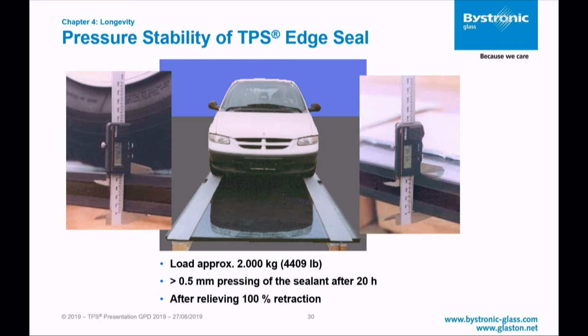Also, since the material stays flexible, what about the stability of the material? In cooperation with an institute, we made a load test of 20 hours with 2 tons. And after releasing the force from the IGU, it got back to the original thickness. So you do not have any disadvantages. Stability is similar to a standard spacer.